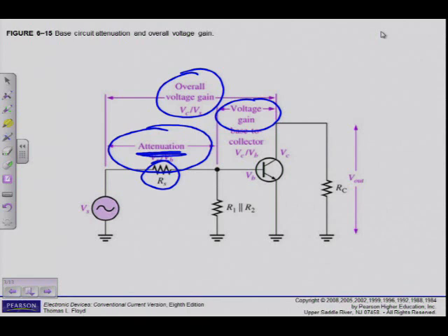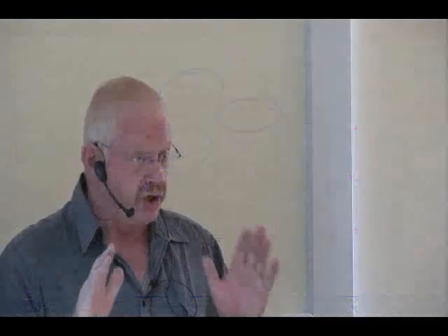And in this specific case there is no RL, because if there was an RL, then RC would also have been in parallel with RL. But now I can see it's only RC on the output, so in this specific circuit no load is connected. That's why I always said you always have to look at the specific circuit that you work with. You can't include an RL if there's not an RL given in the circuit.